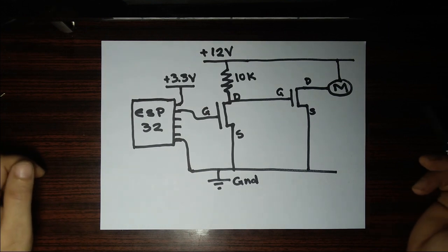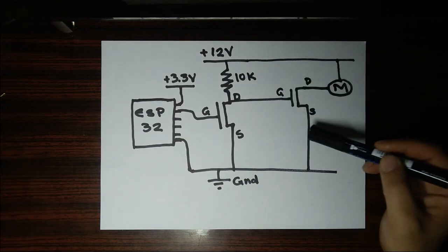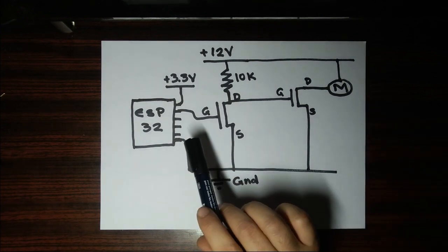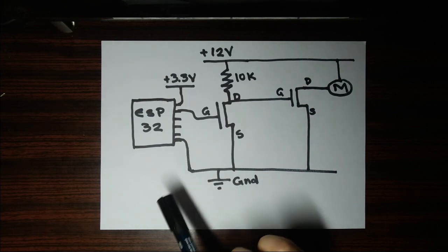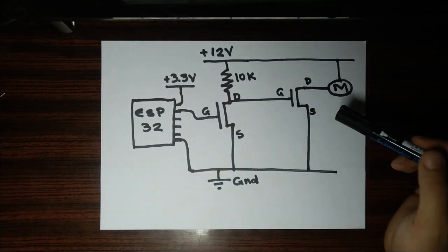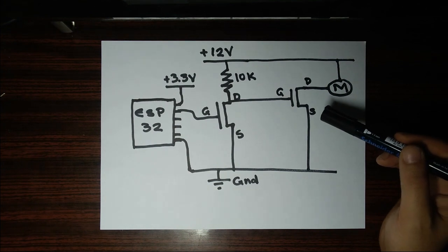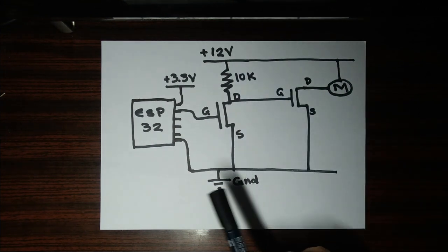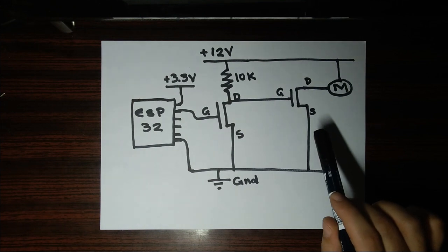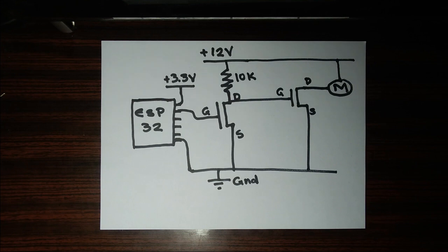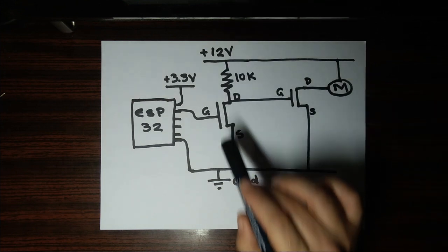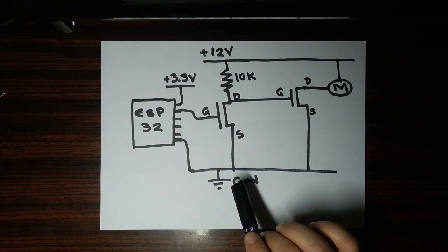Imagine, for example, the scenario where we want to control a big MOSFET that requires at least 4 volts to turn on, with the output of an ESP32 microcontroller which works at only 3.3 volt levels. The pin on its own cannot drive the MOSFET as it can only reach 3.3 volts. Putting an NMOS NOT gate in between the pin and our MOSFET, and using a small signal MOSFET here which turns on with merely a plus 1 volt bias on its gate, we can drive the big MOSFET with whatever voltage we have put at the NMOS gate.